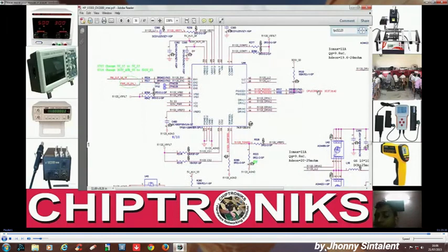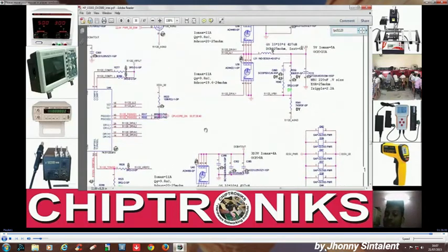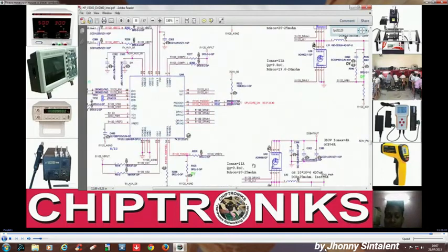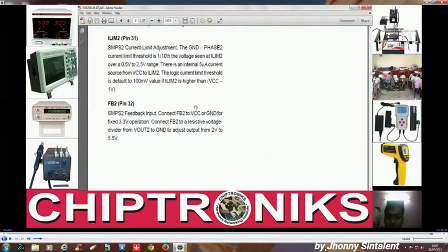And where is this power good going? One of the power good is going to the CPU_on. So here this is different than RT8206L. What are the differences? One, the enable pins, another the power good. This comp 1, comp 2 was not present. Okay, there are 4 enable pins, whereas there are only 2 enable pins, and the LDO switching voltage gets auto started. This was auto start in the previous regulator that we discussed.